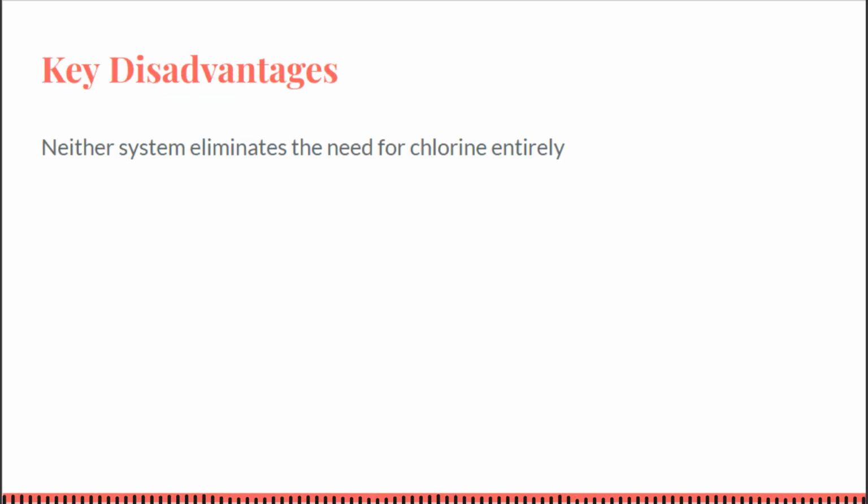Key disadvantages. Ozone alone cannot inactivate certain parasites as effectively as AOP, which has UV light aiding it, so AOP may provide a broader disinfection spectrum. Also, ozone might slightly lower a chlorine residual if oversized or run 24/7 due to its strong oxidizing nature, requiring careful balance. AOP systems have higher initial price and multiple components to maintain.